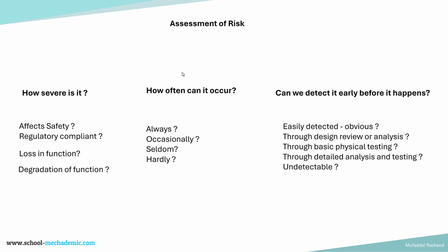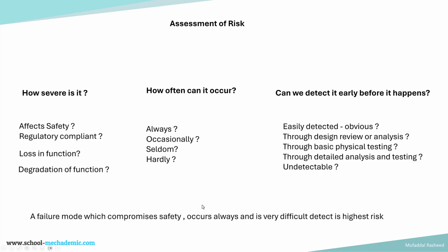You are not able to detect the failure mode even through testing, even through detailed analysis, even through design reviews. You're not able to detect it. That's the highest level of risk. So a failure mode which compromises safety or compromises regulatory compliance, is occurring always and is very difficult to detect, is the highest risk.